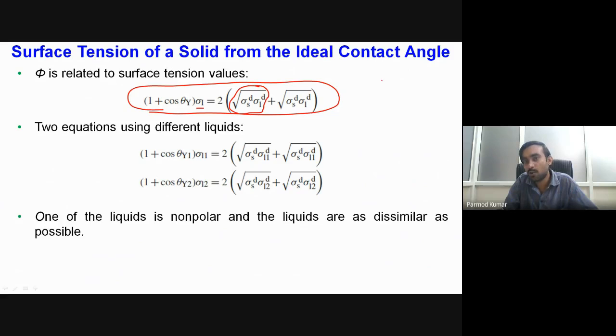So now only the two fluids in contact matter, one is the solid and one is the drop liquid. That is why the value of phi is determined using this combination, considering the surface tension of the solid and the surface tension of the liquid. And apart from that, there is one typo here. This should be P. P is the polar component of the surface tension of the solid and of the liquid.